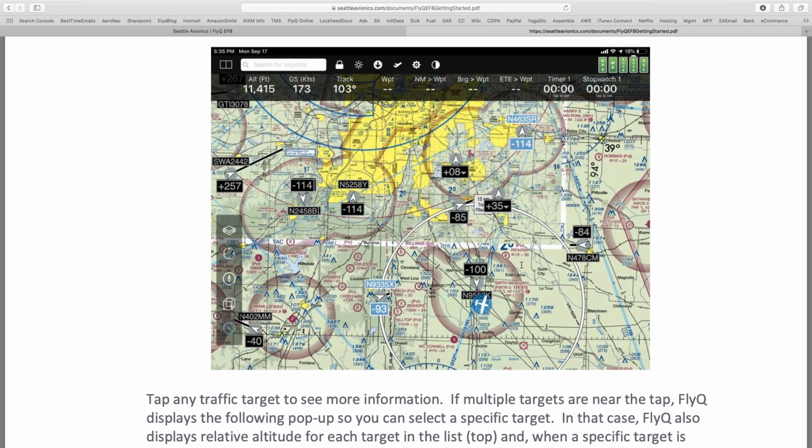So the FAA will be broadcasting your position back. You're looking at it, and since it's usually a couple seconds behind you, and there's also an issue to do with pressure altitude versus GPS altitude, you end up seeing essentially a shadow of yourself. So it looks like there's some other aircraft a few hundred feet away from you. Kind of annoying, actually. So if you have ADSB out, which is to say you're broadcasting your tail number into the sky, you go into settings, to something called tail number to ignore. You type your N number in there and FlyQ will filter that out automatically.